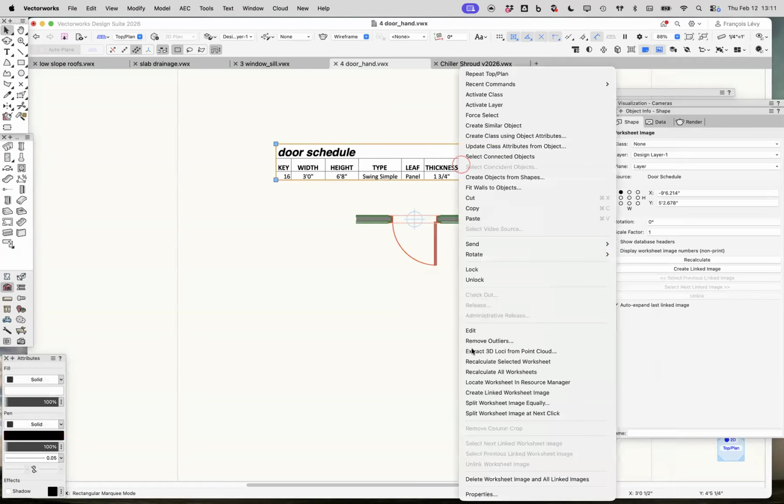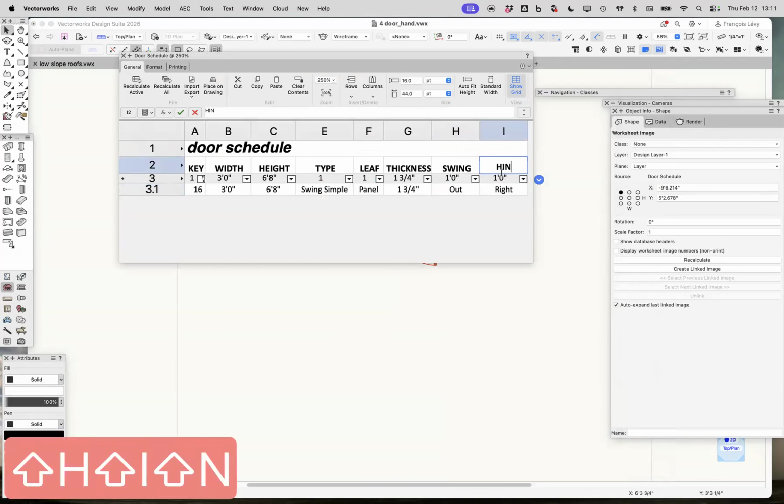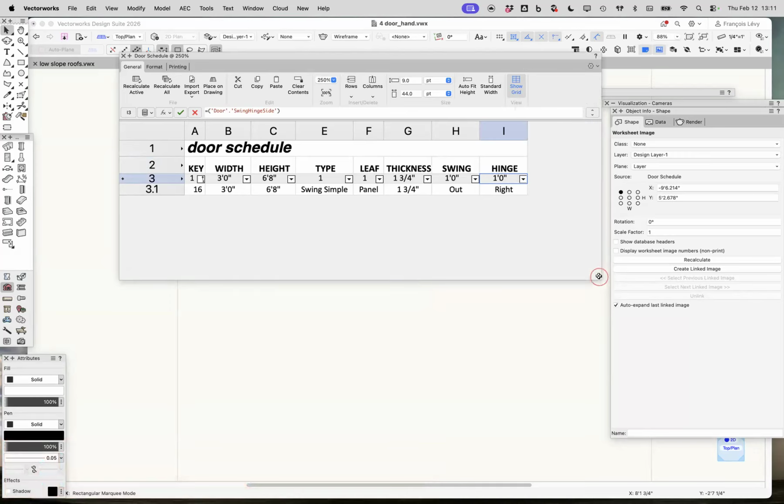So my schedule's incorrect, because I'm labeling that as handedness when really that's the hinge side. Exactly. But what you want is to show handedness, which is always going to be opposite the hinge side on an outswinging door. So I like to show the hinge side and the hand and the swing out. I tried to put another column in showing the hand, and it's really only for hardware, if you use a lever, paddle. Sure.